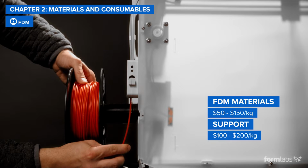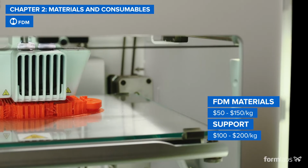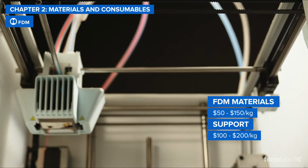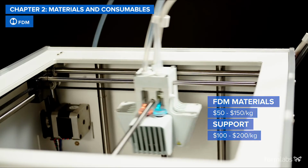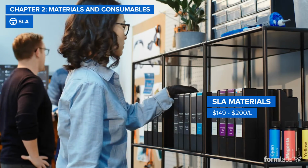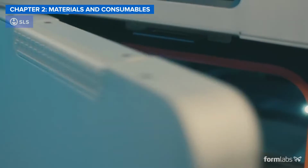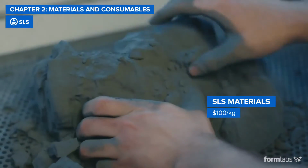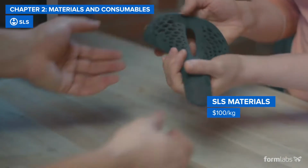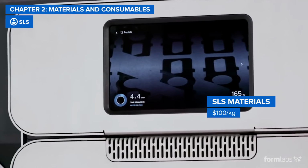On average, FDM materials usually cost the least, but a higher need for support structures and discrete support materials that are required for more complex parts can substantially increase material costs. SLA materials usually carry a slightly more premium price tag. SLS material costs are in between FDM and SLA, but because SLS 3D printing requires no support structures, and unfused powder can be reused, material cost can be significantly lowered.